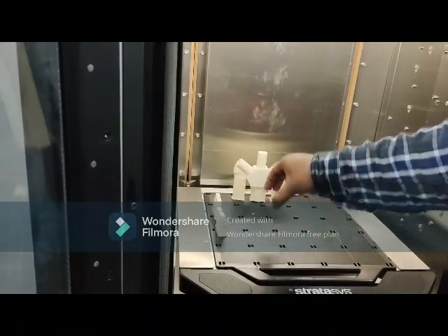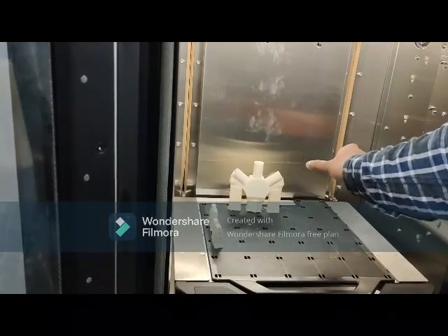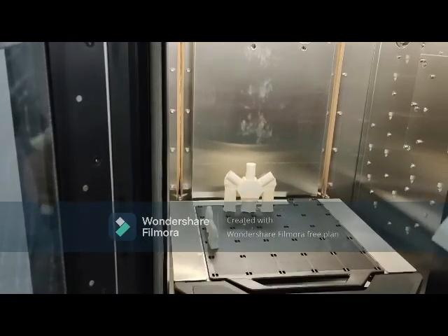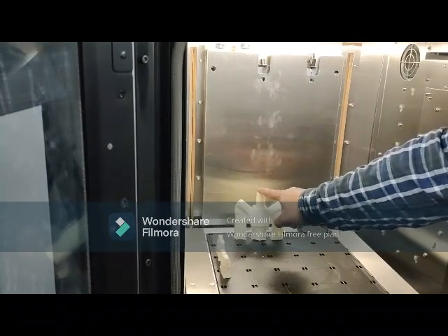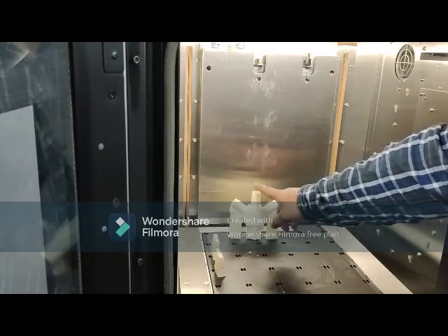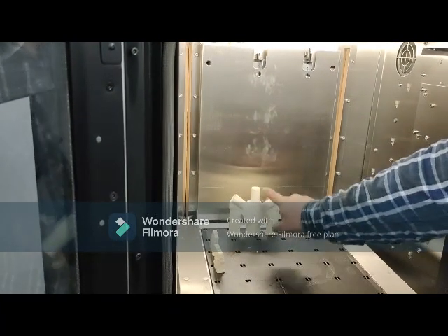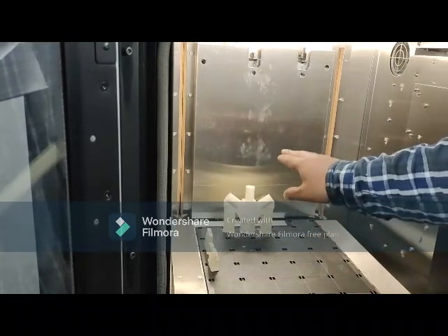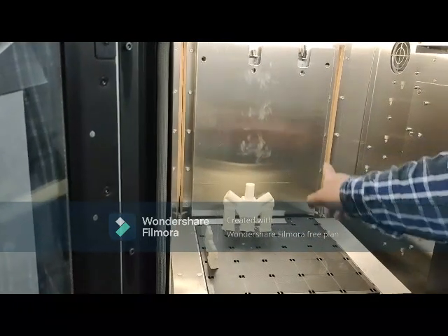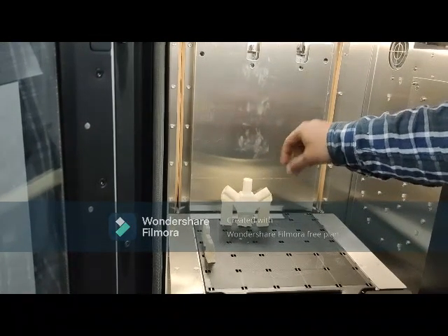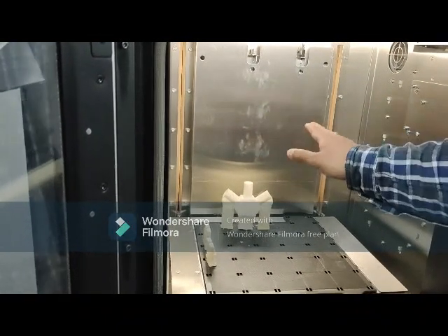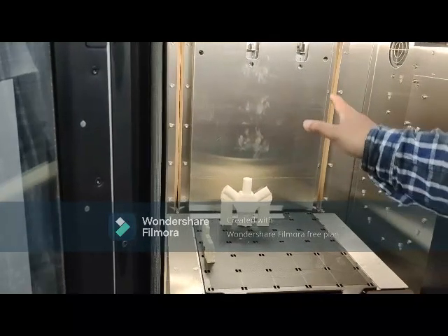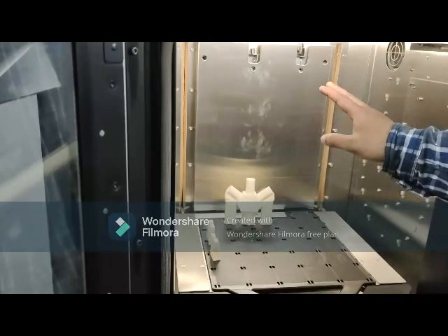Gradually when we are moving and building the thing, the purge tower will also come up, and it will maintain the same height. So what is the reason of giving the purge tower? The purge tower is basically given to check the height. It is continuously correcting the height of the 3D printed part. Like suppose we have this one around 65 mm or 55 to 65 mm height we have here. So the purge tower will continuously check the height, whether, when the nozzle is printing the thing, the height is kept constant or not, or it is changing the height, some kind of problem we are facing. Basically one reason.